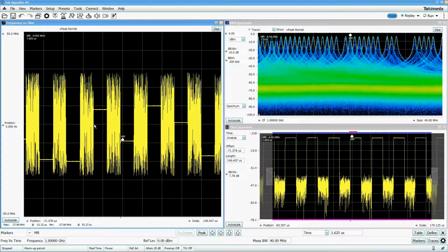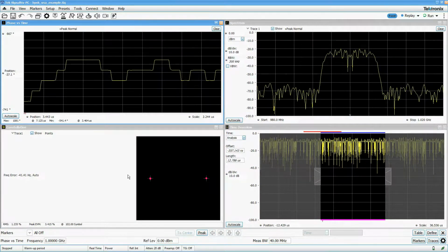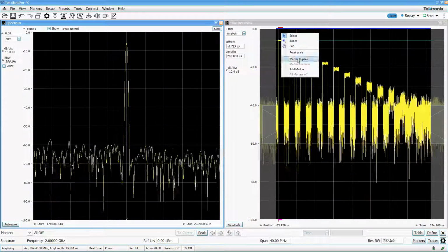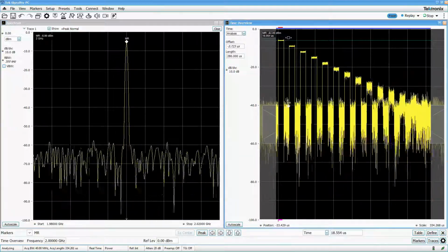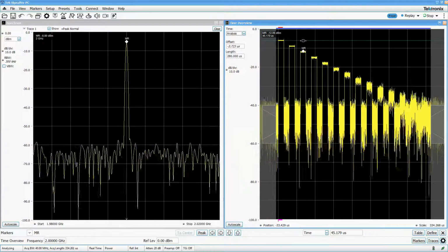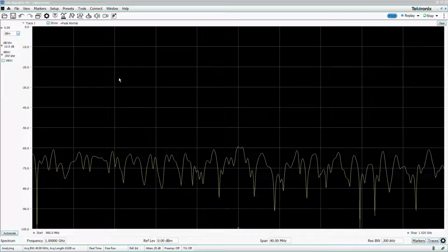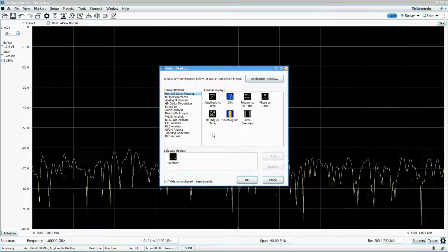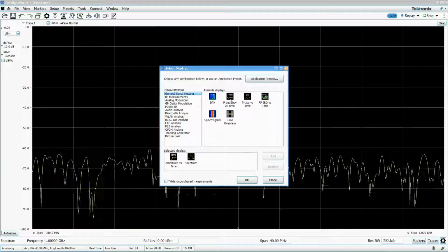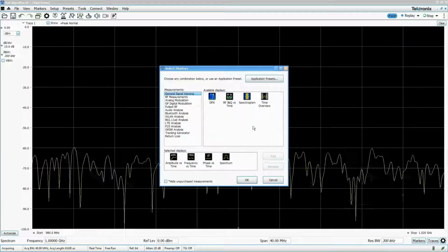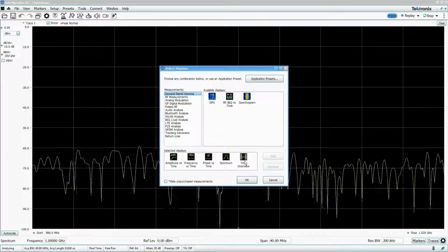Confirming the hop pattern of a frequency agile signal, measuring the phase shifts of a phase-modulated signal, or characterizing the behavior of signals with amplitude changes is difficult or impossible with a traditional spectrum analyzer, but it is trivial with a vector signal analyzer. Since the time domain is important in vector signal analysis, we will be talking about common visualization and measurement tools, such as amplitude versus time, frequency versus time, and phase versus time. We will also discuss the importance of controlling your acquisition time.